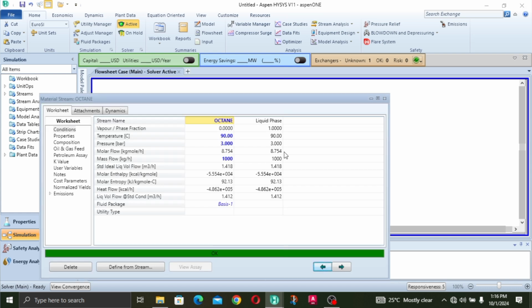So if this time around Basaka is having a flow rate for each bowl, he's having a flow rate of 1,000 kilogram per hour. That's like the amount of hot water inside the bowl. If we're talking about 2 bowls, Basaka would be having 2,000 kilogram per hour in total. So we will be creating 2 streams to be connected to the heat exchanger, but you cannot connect 2 streams to the inlet of a heat exchanger. So we will have to use a mixer to mix 2 streams into a single stream and then connect them. That was our previous content.